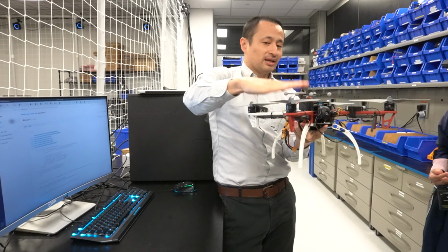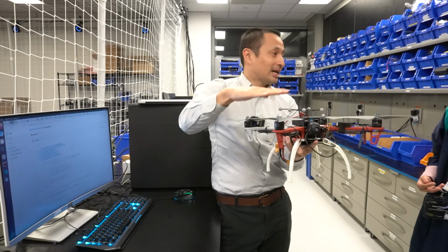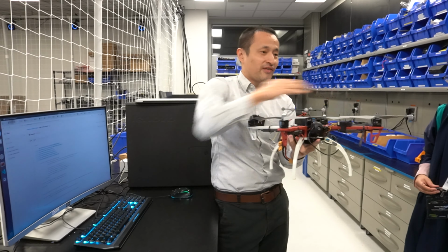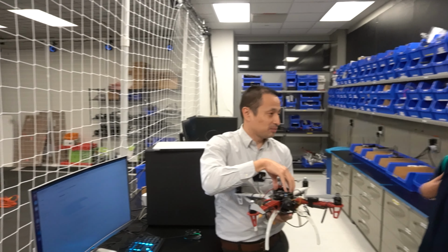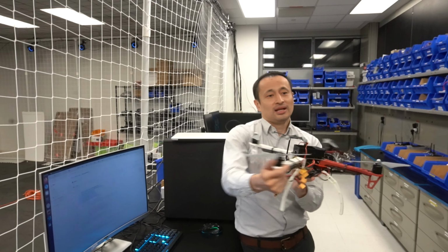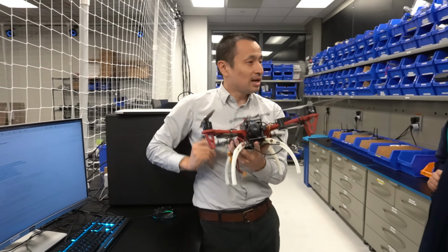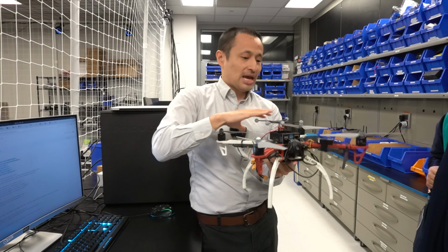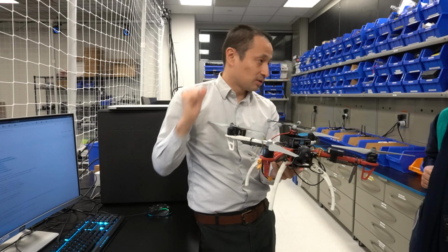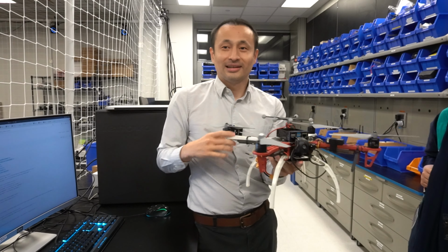But if we start moving this pair a little bit slower, but this one faster, we will create the moment, and the drone will start spinning. So if you can put that logic on the computer, you can make a drone move around its own axis. So now we have full control. We can move forward, back, left, right, and we can move it around its own axis. So we have full degrees of freedom control for the drone. Is it clear? Yes.